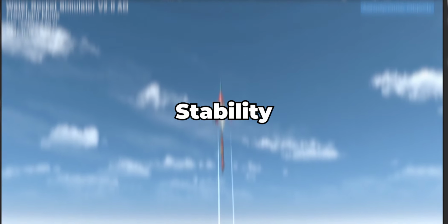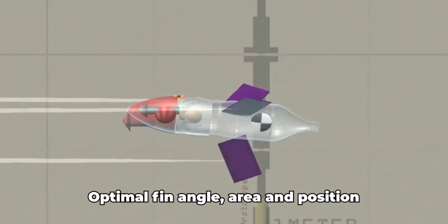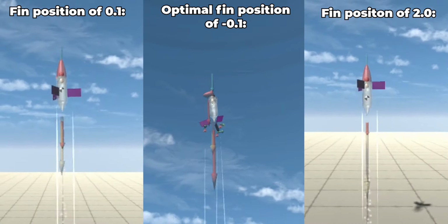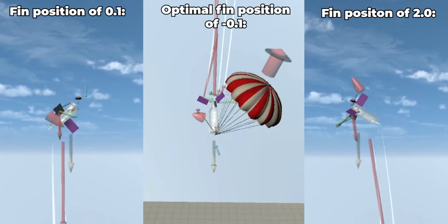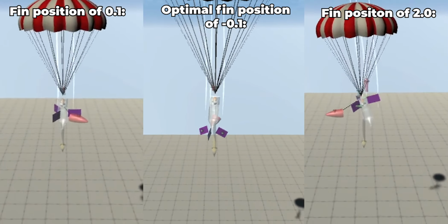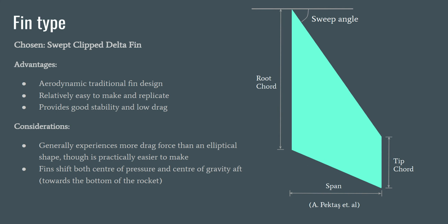The fins of a rocket play a major role in its stability. Fin position shifts the centers of gravity and pressure. For our rocket, our group settled on using 3 fins, offering sufficient stability and lower drag. In Unity, the height where the fins were placed on the rocket's body was varied and tested. With this, it was found 0.16 meters was the optimal fin position. For the fin shape, we chose a simple swept clipped delta design, which retains the aerodynamic advantages of a traditional fin, such as in the simulations, while providing good aerodynamics.